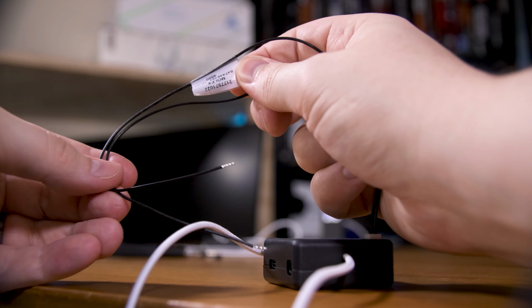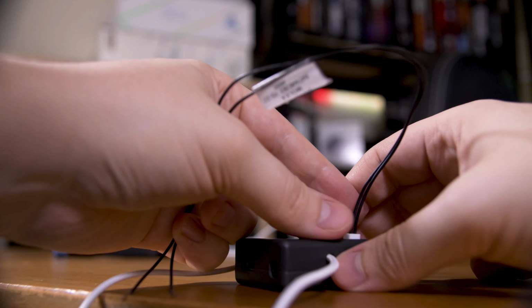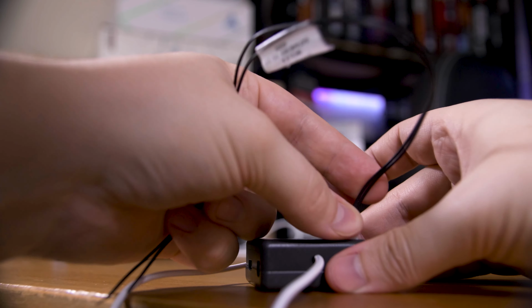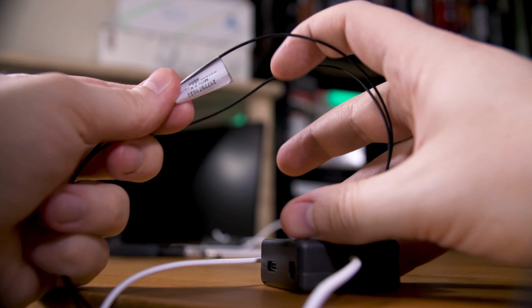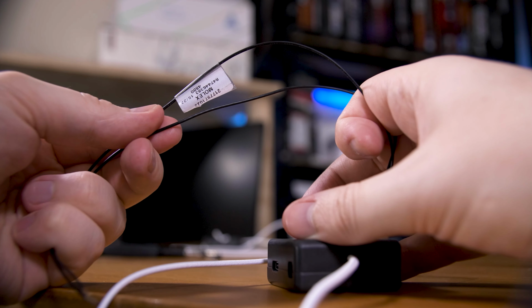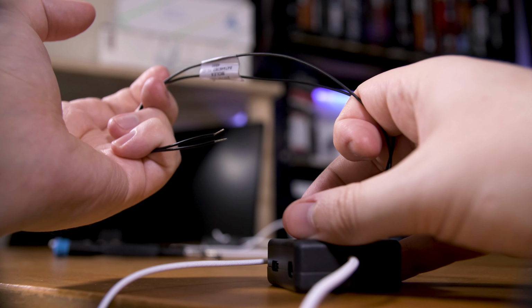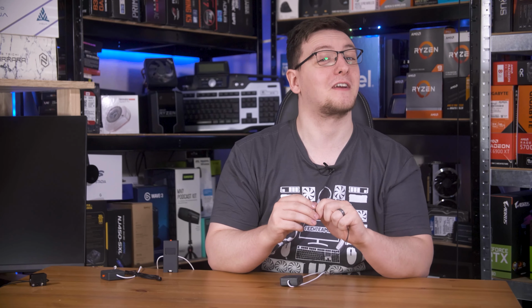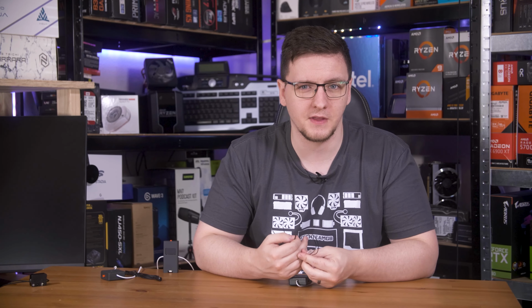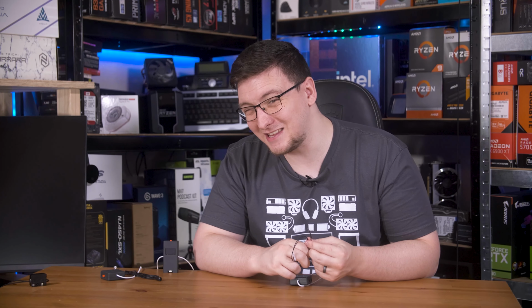If you opt for these fly leads, the one that has the white sticker on it is the positive lead. The other one is just ground. So you obviously connect ground and then supply a voltage to this positive lead, the one with the sticker on it. In an ideal world, you would only supply up to 3.3 volts, as that's what the microcontroller is running at. But because I know that people will forget that fact, I've designed the circuit to fully isolate and protect the microcontroller. It uses a tiny little transistor and 2 resistors, so technically you can supply up to 50 volts and it should be fine, and that is what the transistor at least is rated to.